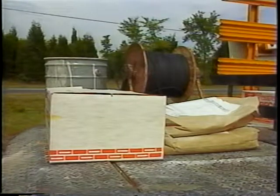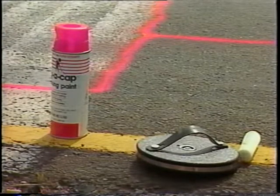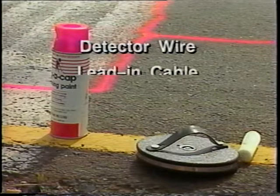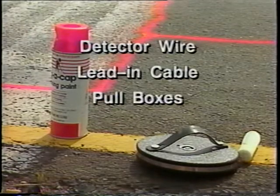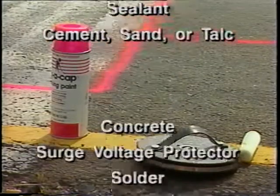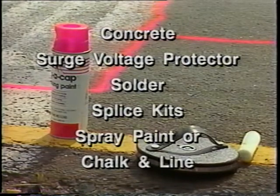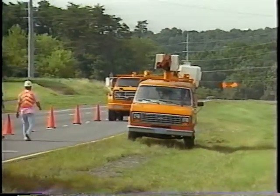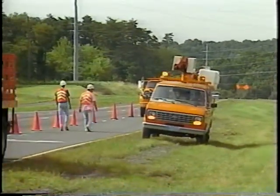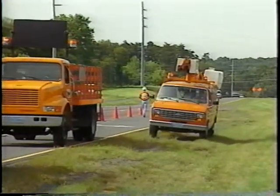any work interruptions. A typical material list for a loop installation includes detector wire, lead-in cable, pull boxes, sealant, cement, sand or talc, concrete, surge voltage protector, solder, splice kits or equivalent, and spray paint or chalk and line. This completes the pre-installation process. Now, let's discuss installation techniques using our example for illustration.